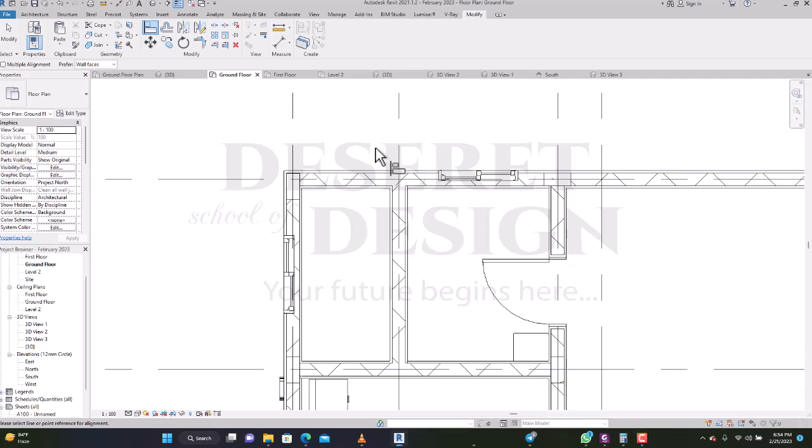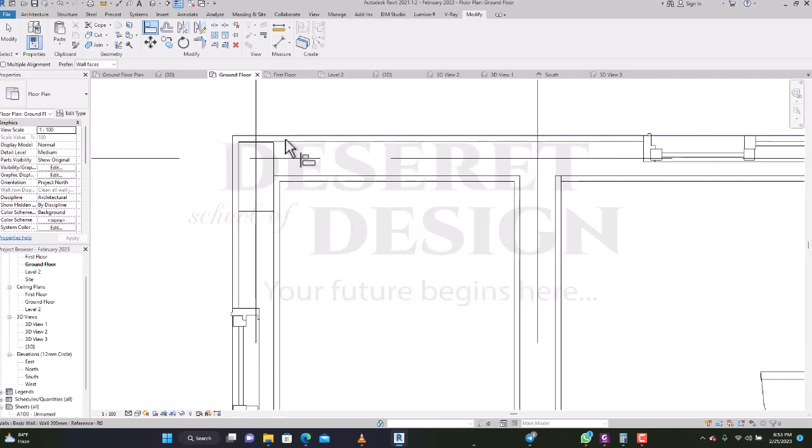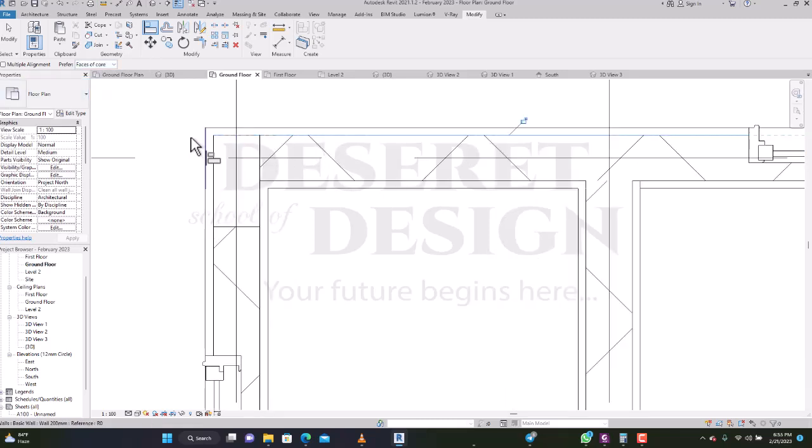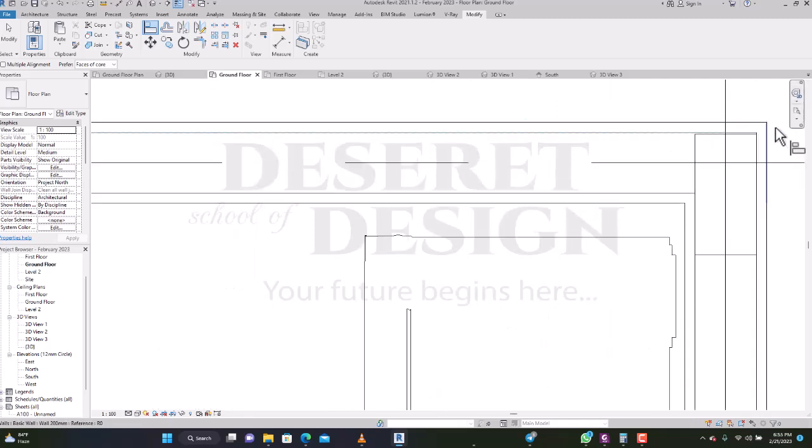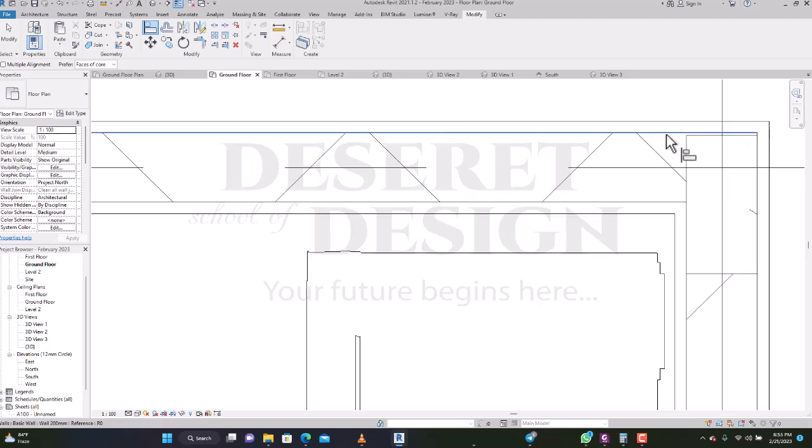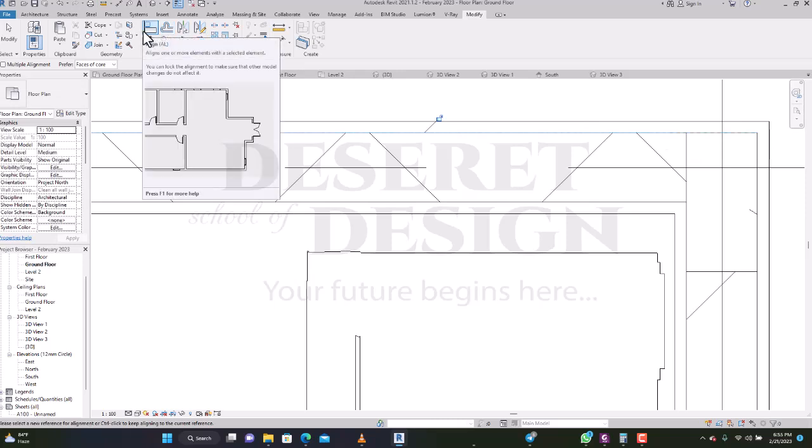So you've resolved your issue. What did you do? Can you see the column? You said you can't see your column. You told me that you had a warning. Yes, I've seen it. So you've seen the problem. When you're placing, make sure you check the placement order. Okay, so now I'm trying to align all my columns well. I'm aligning them at the edges, especially the edges, so they will not be flush. How did you do it? Align to. I'm not showing align. Are you sure? Okay.